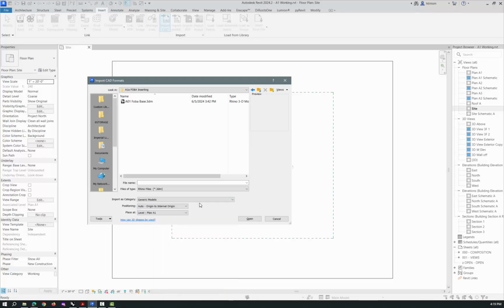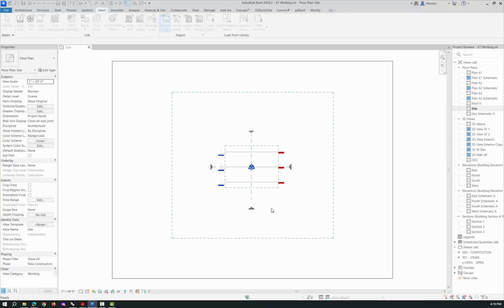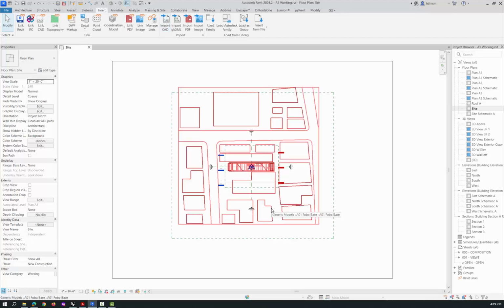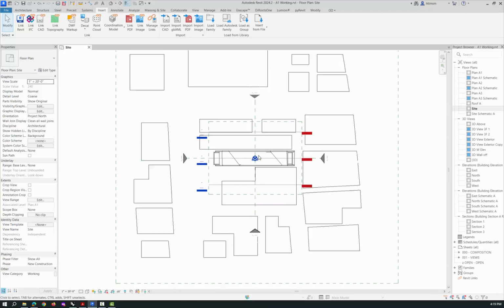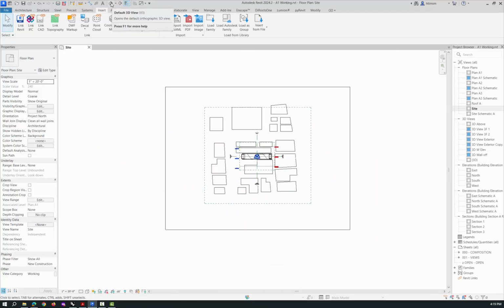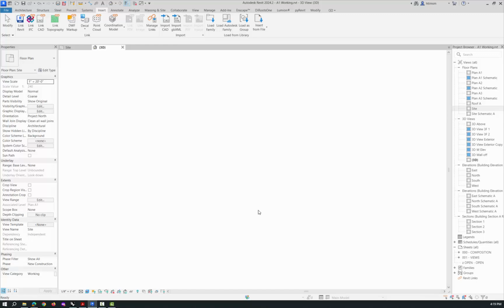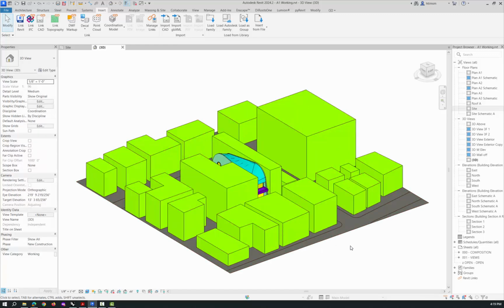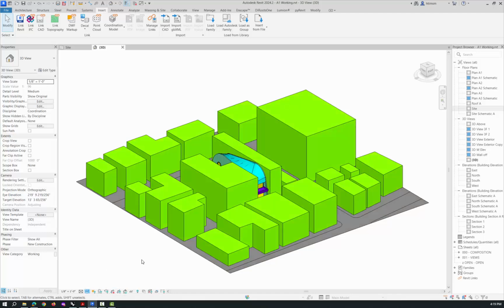It is very important that you categorize it because Revit will not be able to section it. And then if I highlight that and click open, it will think for a minute and it'll bring this guy in. So you can see that it's plopped that guy down at 0, 0. If I go to my default 3D view up here, which is the same as the bracketed 3D view over here, it'll take a second to think, and it'll bring this guy up. Right now, it's in realistic view, so I'll go to shaded. It shouldn't change very much.